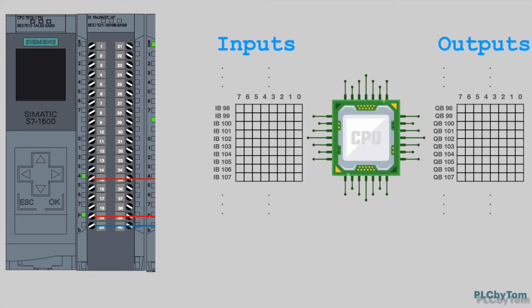For each channel shall be assigned address from address range of the CPU, and in this way CPU exactly knows distribution and addresses of each channel, and CPU can read status value from any input channel and send command value to any output channel. Number of bytes required for addressing the I/O module depends on the I/O module.